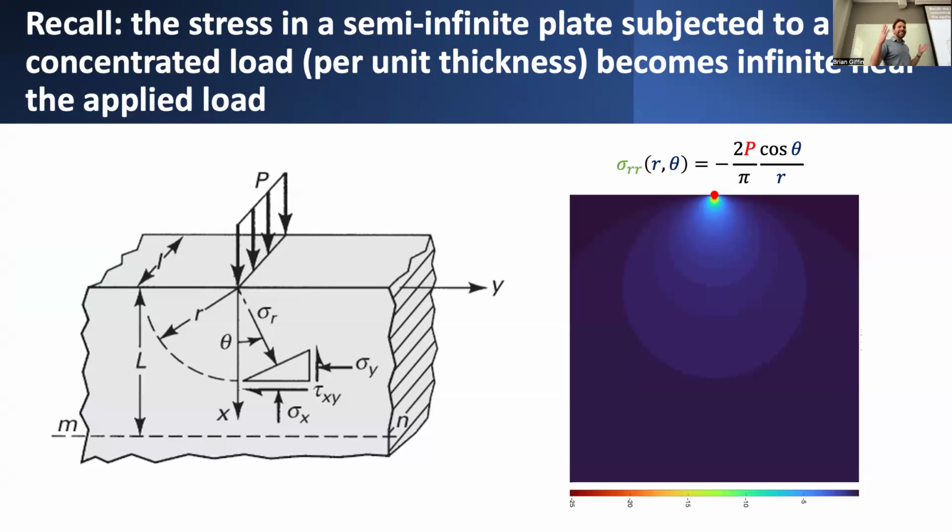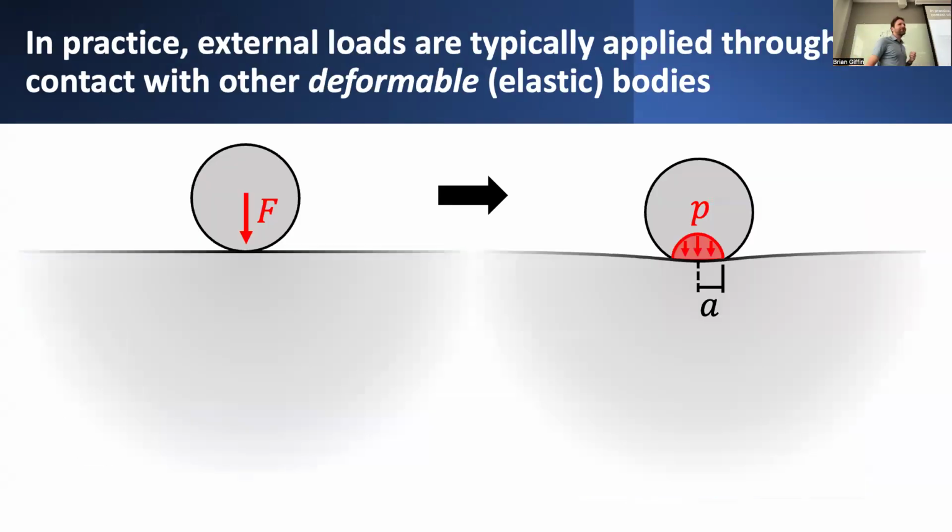Now, in practice, that's never really what the stress distribution will look like. In practice, you'll never have a truly concentrated load applied to a boundary. And it has to do with the fact that, well, how would you truly apply some concentrated load? You could think of a knife's edge or a wedge, pressing down like the tip of a cone into some infinite elastic medium on its edge. And maybe that way you could try to emulate the behavior of some kind of localized force.